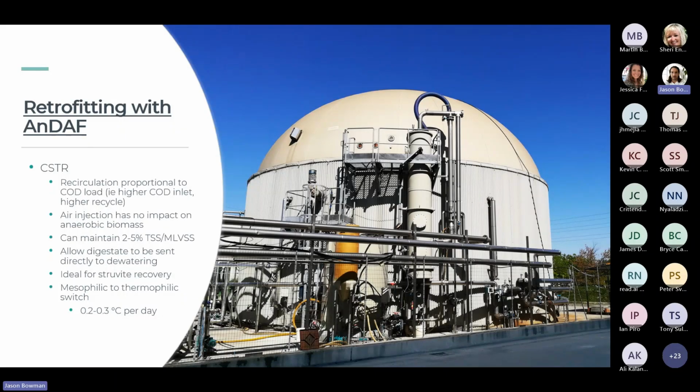The other thing to think about with these systems is they're not really designed for mass transfer. The alpha values, if you get into aeration design, basically the type of air that you're putting into this unit is absorbed very, very quickly, and there's really no residual DO in these types of processes. So not only the saturation values that we control, but the solids loading per unit area with this type of DAF is actually 2 to 3 times higher than what you might find in a DAF system that would otherwise be in a normal biological process, primary treatment, secondary treatment of aerobic systems as an example.